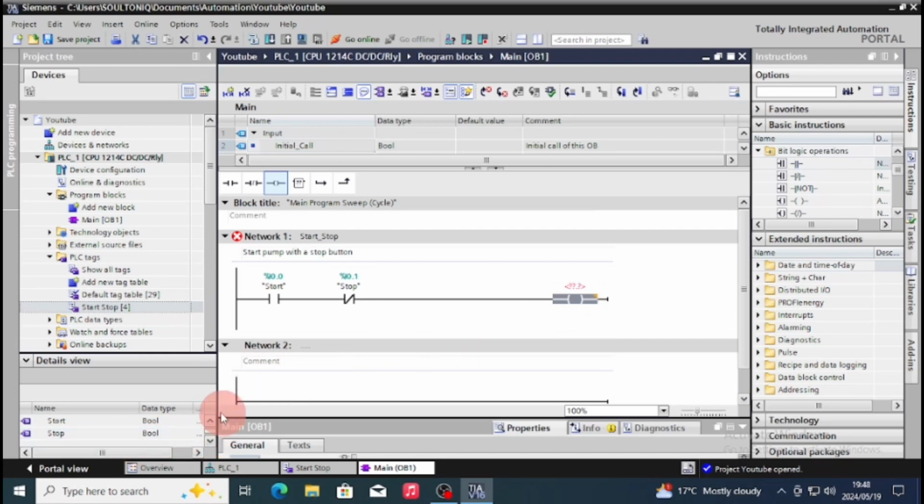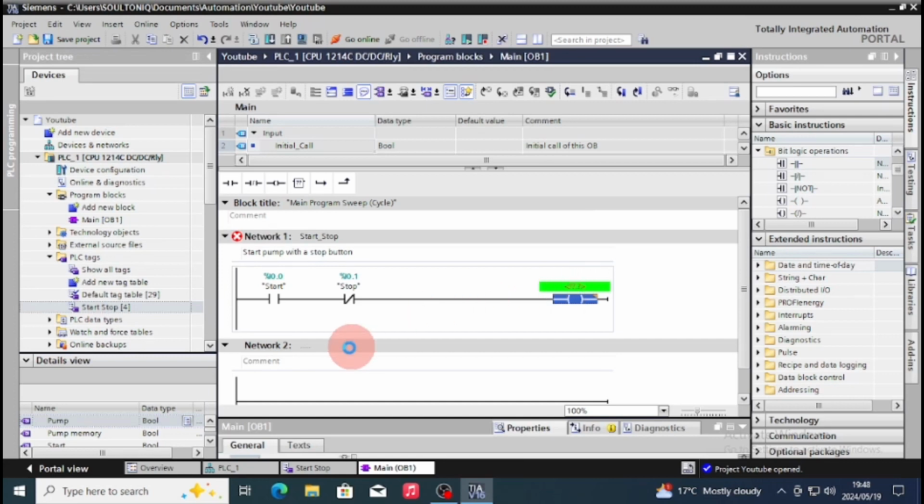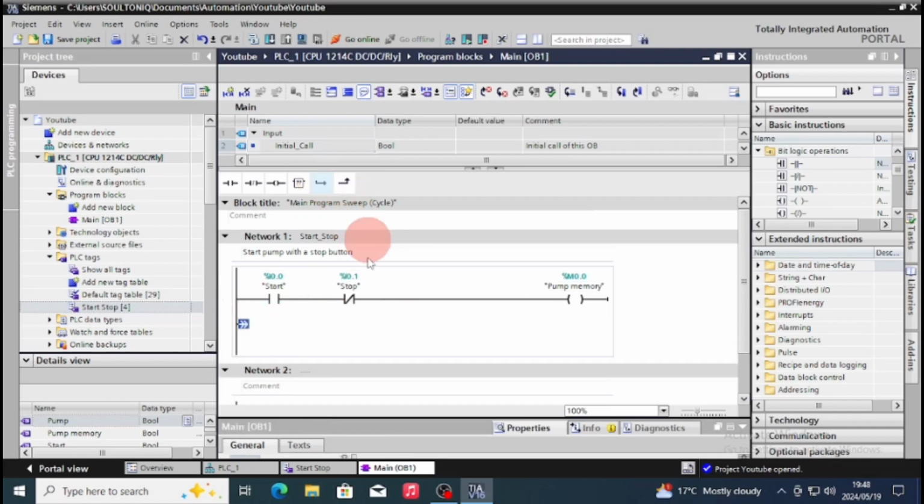Now we'll put our output. When you click at your text table at the far bottom screen of your TIA portal, you'll have your tag, and then you can just go there and drag and drop your tags. Okay, from here you need to put a retainer, not a pump, so you can just use the other option of tags. Just press on it and then it will show you all the tags that you have. Then you just press the tag that you want.